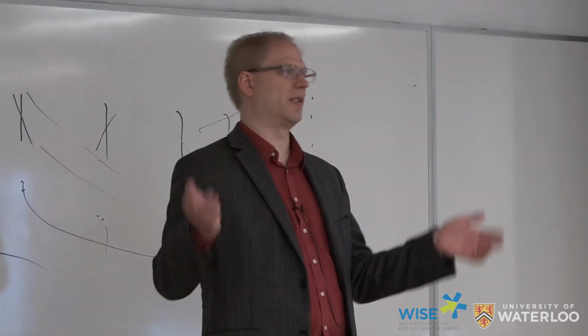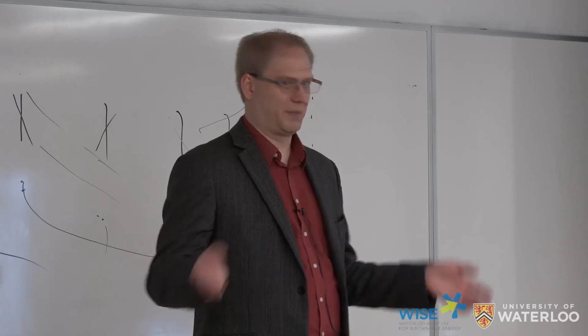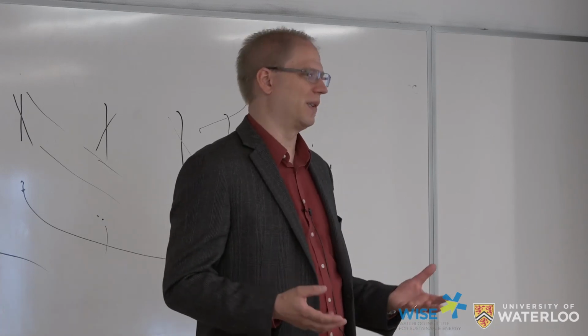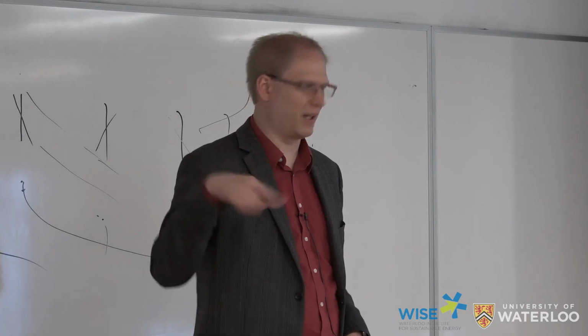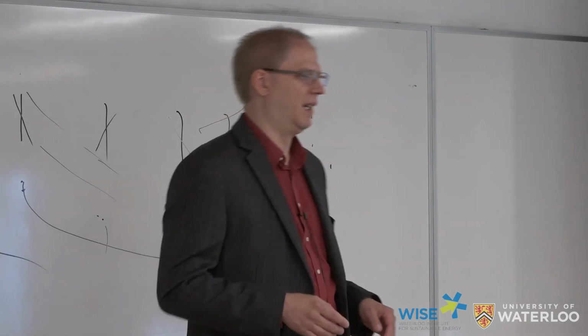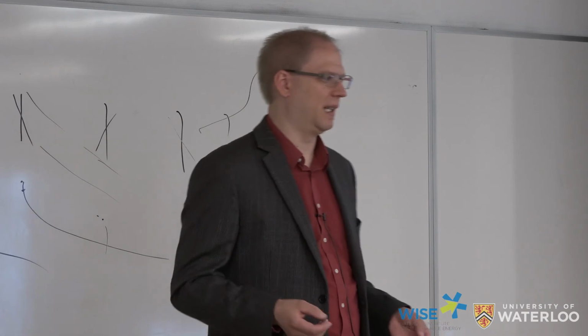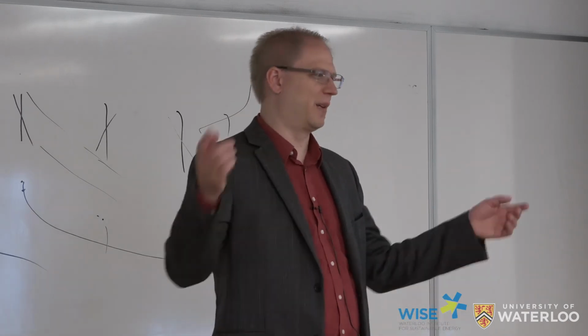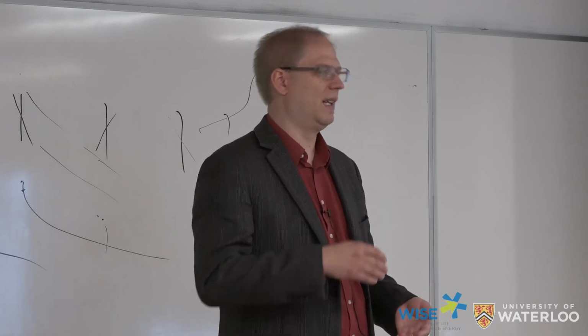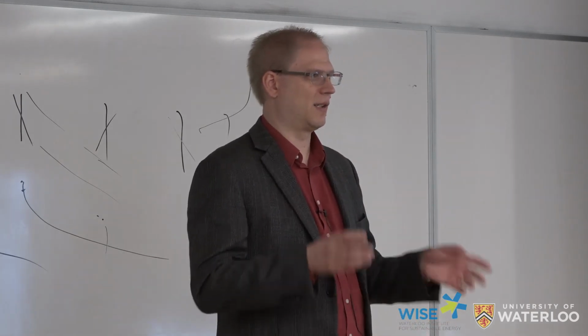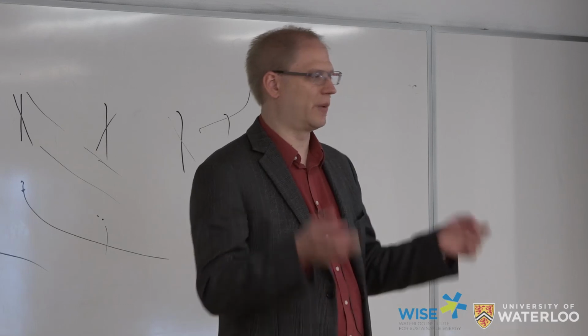So I say, what are the unknowns of my turbine? Aerodynamic profiles, that's probably the most uncertain, lift and drag. Obviously, in a 2D sense, from a wind tunnel, we know it, but in a spinning environment, it's very much uncertain. Structural damping is another big one. I always just assume some number. I don't really know what the real answer is, and so what's the sensitivity of that? There are stiffnesses and natural frequencies that may be different and so on.